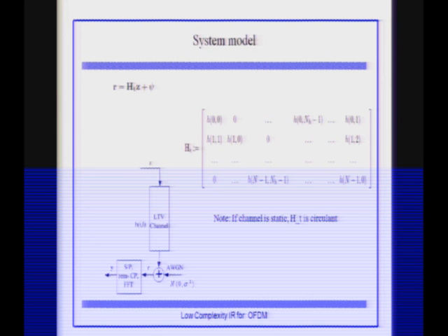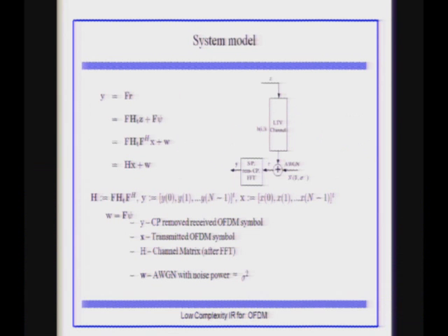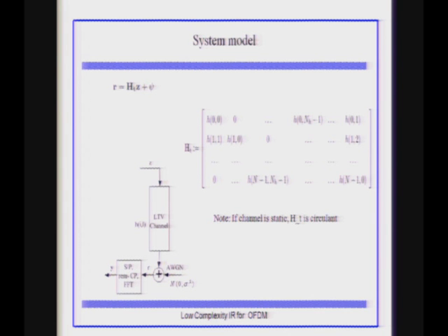So we get R, we model R, and so what does circular-like mean? It means that if the channel were static, then it would be circular. That's right. If the channel was static, these numbers would have been the same. And if that is the case, then this row will be a rotated, shifted version of that. So then it is truly static.